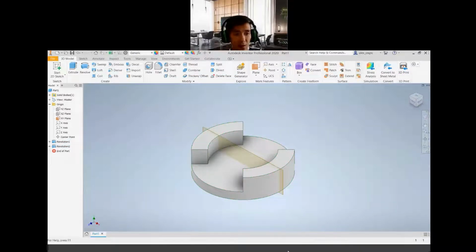So if you have a look at your geometry again, you have another Revolve feature, which is inside, in the internal part of this part itself. Okay, the next thing I would like you to do in order to create the third Revolve feature here: this default work plane, now you can turn off the visibility already. Go to the browser, then turn off the visibility. Click once more, then that's all. So it's not in your display anymore.